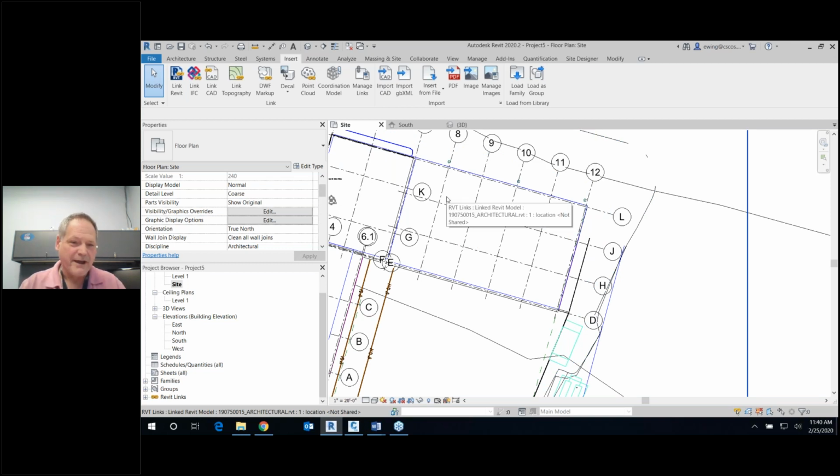So when we publish the coordinates back to our architectural model, and we go to our site model and our architectural model, that will be rotated to true north, but our sheet views that we're working on are going to be rotated to project north, just however we started that model in a linear manner, if that answers your question.